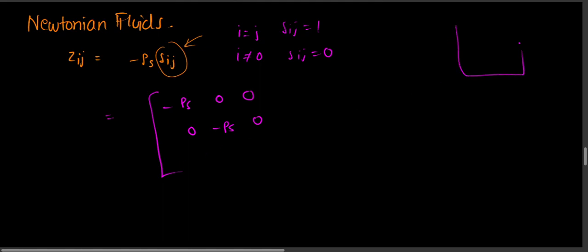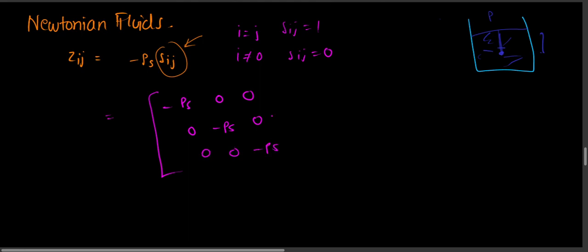If you have, let me do that in blue. So if you have water like this, and you have some height, you can calculate the pressure here, right? P plus rho g h, with P the atmospheric pressure plus rho g h, where rho is the density of water, and so on. So that is the static pressure. So again, I can write this down like this.